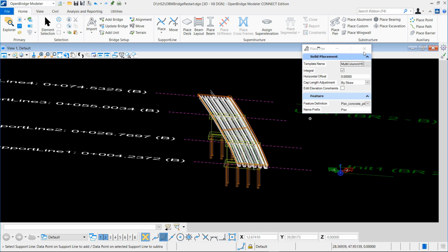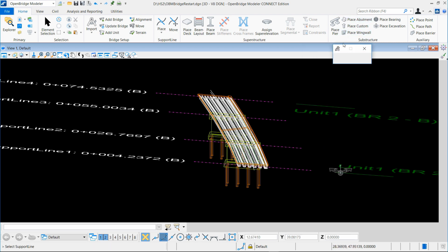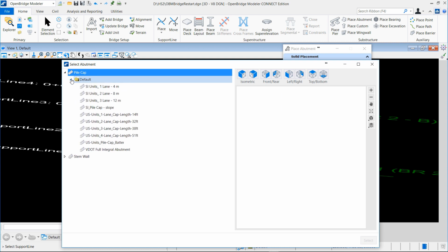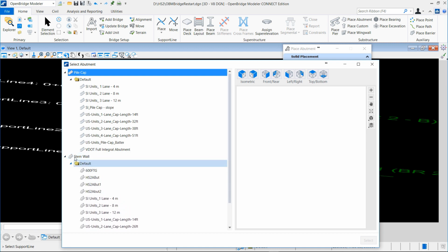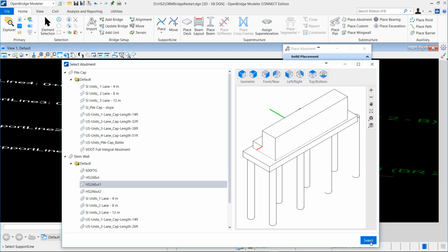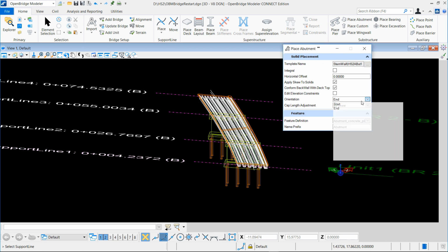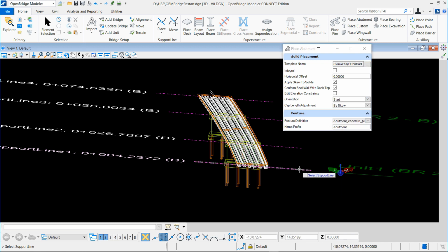We can have these piers adjust themselves automatically to the width of the deck, but as we have different skews, the cap is adjusted automatically, but the wall is not. That's why I have two different piers, adjusting by hand the width of the wall supporting the cap. In the same way, I have also defined an abutment which looks like the one from the model I was given, but which is not exactly the same, and we will see how we handle this afterward.